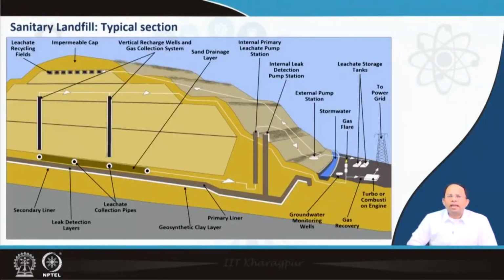So this is roughly the section of a typical landfill. You can see different components to it. For example, this is sort of an area fill method, but you can also call it a modified fill, because obviously some excavation has been carried out over here. This is a drain given at this particular edge, and these are those benches that we talked about, right? And these are the lifts. You can see in each lift, the landfill has gone up.